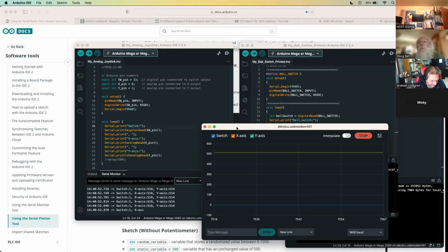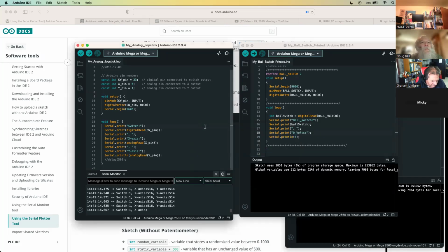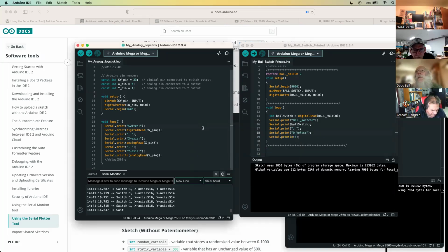They don't have to be using a clocked serial protocol in the chip itself. It could be that only if you get to a UART or out to a serial port that baud rate even means anything. Well, let's see if we can do it. That's just what I was wondering, if the serial print itself might be limited to a particular speed.